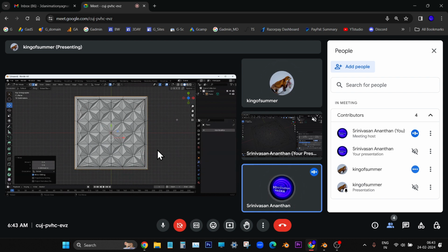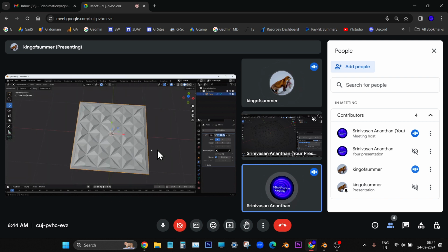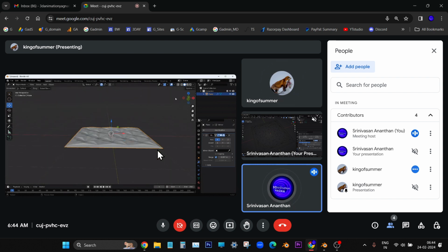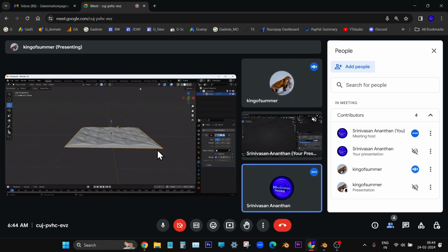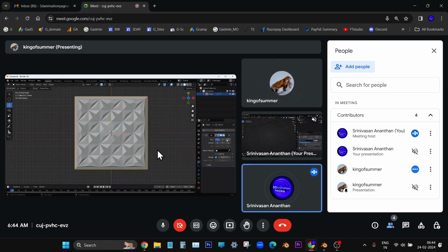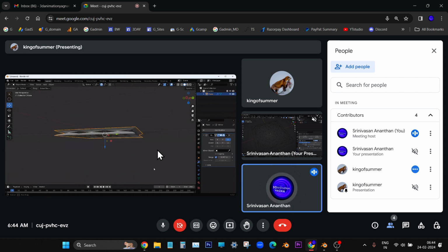Go to object mode and select the object, add modifier, generate menu, mirror modifier. In this we have to duplicate in the Z axis. So press the Z axis in the modifier section. No, you need not move it. Switch off the X axis. Now see, it is replicated, but this is not the way it should replicate.